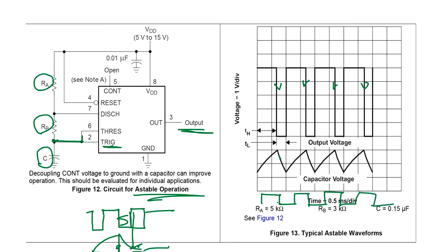So we can make an oscillation with an RC constant oscillator, and we can use this as a slow clock for controlling various things, like, as I said, a traffic signal or a wiper of a car or whatever. This is the idea of the circuit, and it's very cheap. The 555 is like a 20 cent IC chip, and we can make this one.